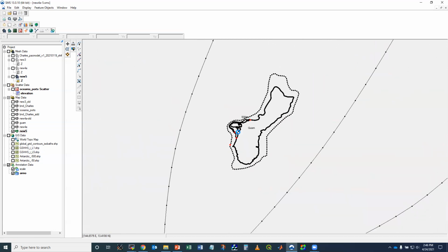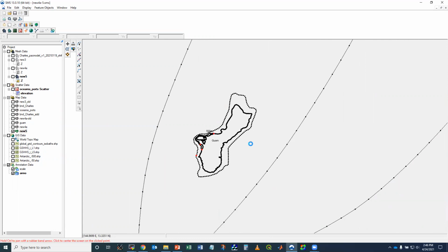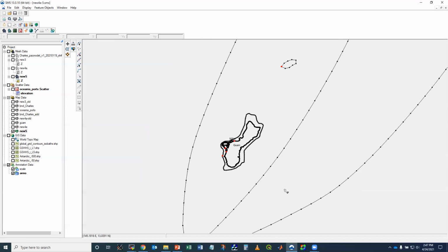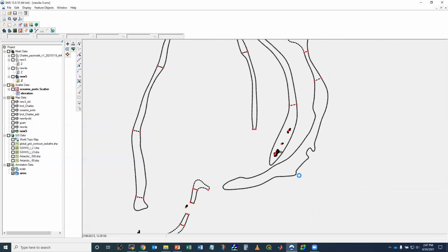So that's basically the steps you should follow if you want to refine other islands. First, pick a target resolution. And if it's significantly finer than 1 kilometer, you may want to consider adding an auxiliary arc if the local bottom slope is steep. If it's very gentle, you don't need to add that, because the resolution will automatically, smoothly transition to the add-in regime. So you don't have a very fine resolution in the deep ocean anyway.